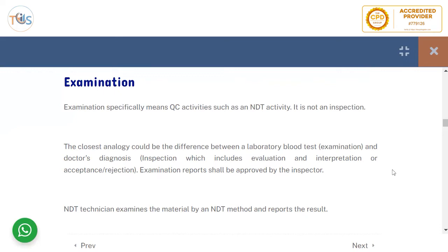So he finds out the type of discontinuity and its location. When he does the interpretation, if the NDT examiner is allowed to do that, he compares the discontinuity he discovered, based on size, type, and location, against the acceptance criteria, and notes in the report whether it is acceptable or rejected. If it's rejected, it needs to be removed and the part repaired, or the whole thing needs to be discarded, depending on how they decide to go about it.